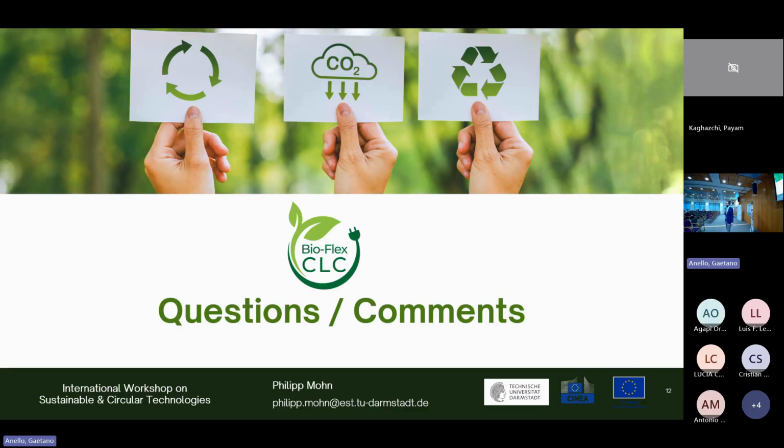The tricky part is, here in the pilot plant, a lot of boundary conditions interact with each other. You cannot just set the temperature, because the temperature is based on how good your conversion is. If your conversion is very good, your temperature will be very high. If your conversion is not so good, your temperature will be cold, and this will make the conversion even worse. So it's difficult to compare this with a lab scale plant where you just install electrical heating and then you can operate the process at whatever conditions you like. And so there you can definitely have better.